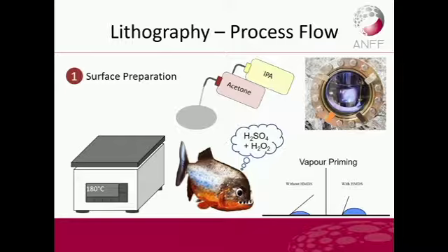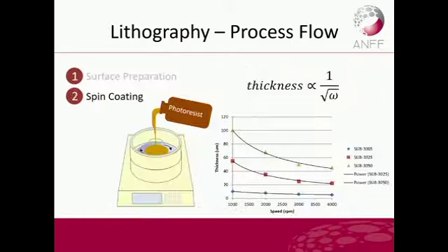After you clean your wafer, you need to prime it. To prime it, you need some sort of a vapor source, such as HMDS, or you can use the titanium primer to coat the surface with titanium particles, so you can achieve a certain contact angle, which works very well for your photoresist.